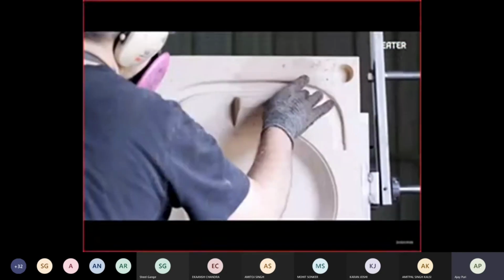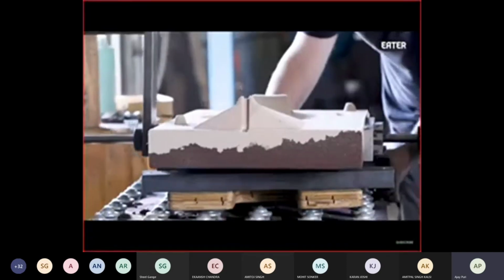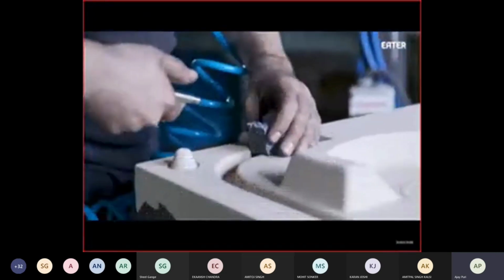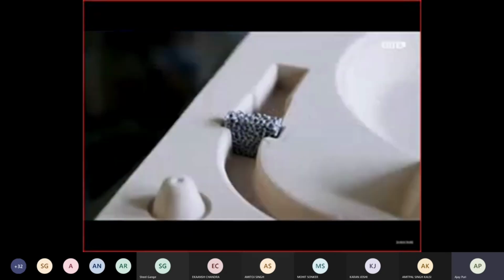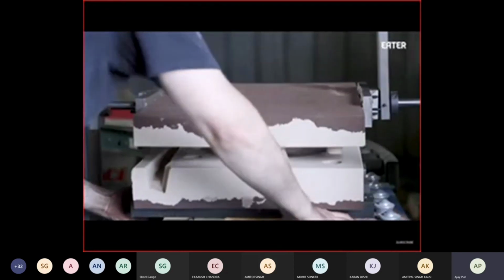There are a lot of details to the pieces that need hand finishing and need the types of molds that we make. We add a ceramic filter to the gate. It's a little piece of foam, so it filters any impurities that are left over, like the iron oxide film that forms on the surface of the metal.